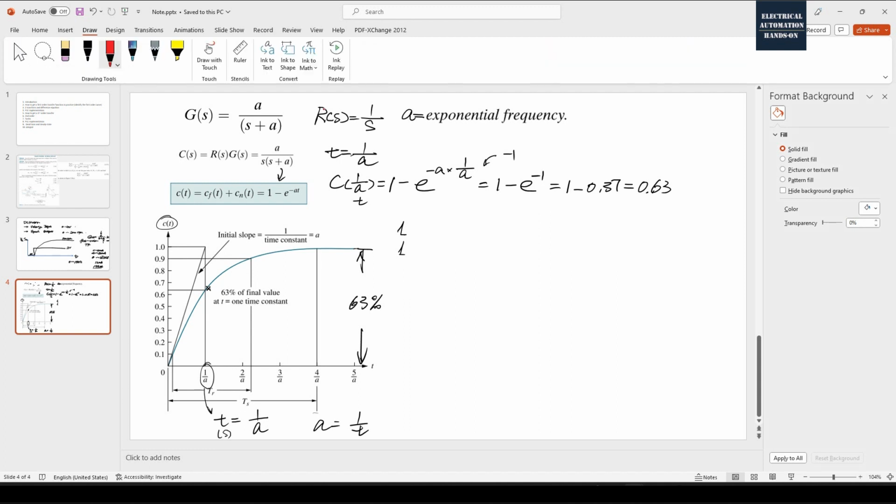Leveraging this curve, once we have this K and we can get the a, once we have this a parameter, then we can get this first order transfer function. Apparently, this is also a gain here. I can explain how we can calculate the gain of this transfer function.